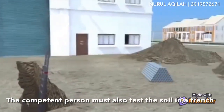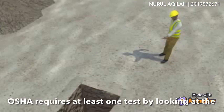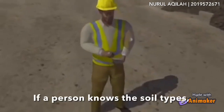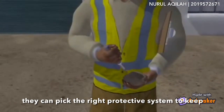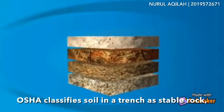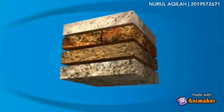The competent person must also test the soil in a trench. OSHA requires at least one visual test by looking at the soil and at least one manual test by hand. If the person knows the soil type, they can pick the right protective system to keep workers safe when they're in the trenches. OSHA classifies soil in a trench as stable rock, type A, type B, or type C soil.